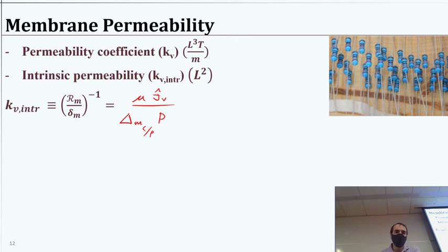Okay, so the first subscript is the location. The second is at an interface between X and Y, whereas concentration and permeate there. All of that is divided by the thickness of the membrane. Essentially what we've done here is incorporate that resistance term. I believe all of this here is that membrane resistance, and we still have the thickness at the bottom. So that's another way we can write that.